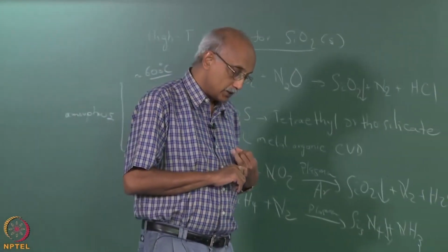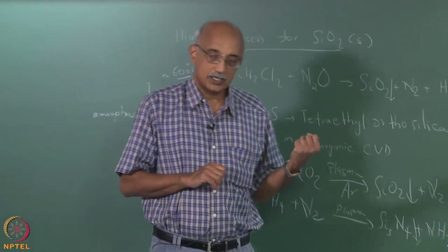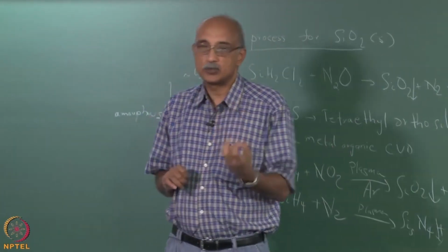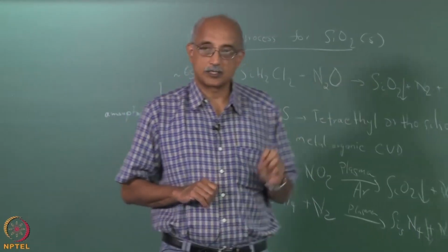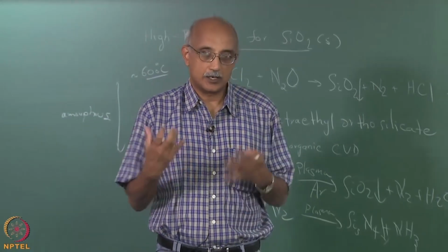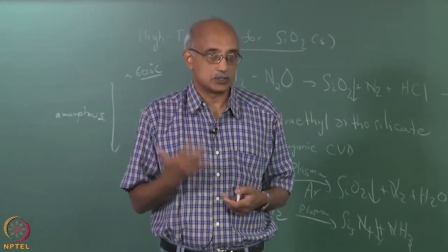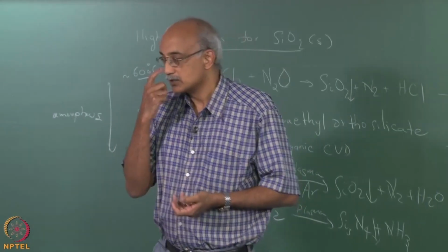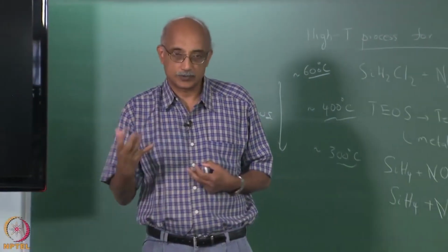The second one is that they enable us to essentially getter any ionic impurities that may be present. So, the boron and phosphorus that are present in this glass matrix will scavenge any ionic impurities and prevent them from causing corrosion or other adverse reactions. So, they improve the chemical inertness of the glass.